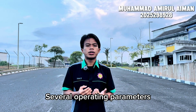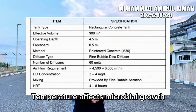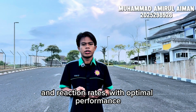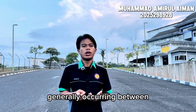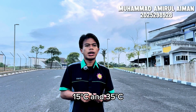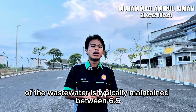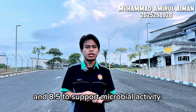Several operating parameters influence the performance of the activated sludge process. Temperature will affect microbial growth and reaction rate, with optimal performance generally occurring between 25 degrees Celsius and 35 degrees Celsius. And for the pH, the wastewater is typically maintained between 6.5 and 8.5 to support microbial activity.